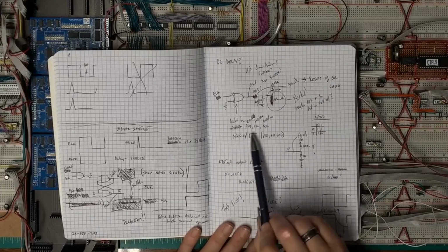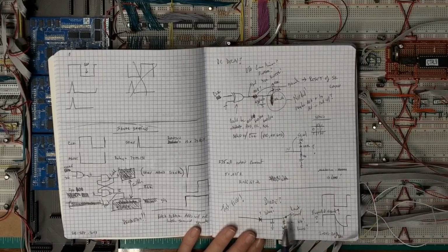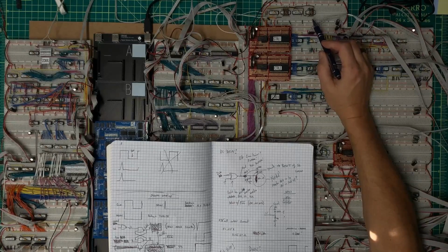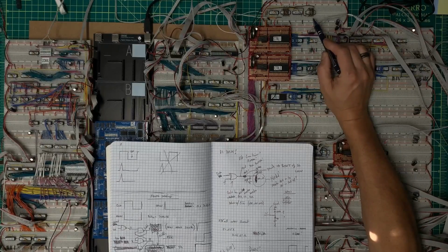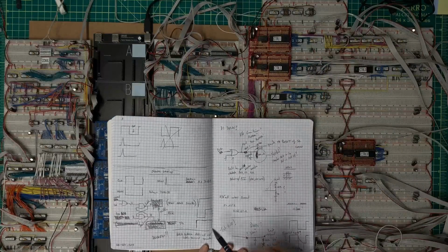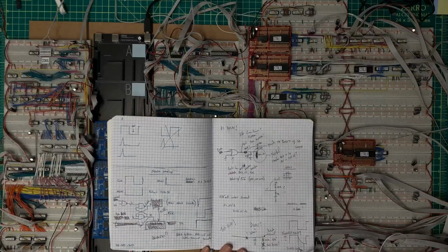Then I started looking at analog ways to address the problem, including RC circuits and then a diode with a capacitor, thinking I might end up having a signal that looked something like this down in the corner. But after thinking on it for a night or two, I finally realized I have everything I need up here off the top of the board where I actually shape the spike clock. I'm inverting the clock a number of times, about 12 times, and that then produces the delay that I need in order to get both the latch signal and the assert signal. It's just a matter of how big of a delay do I choose from.